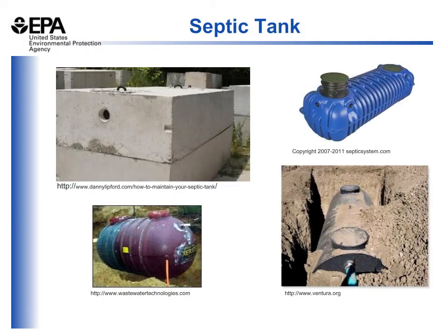Septic tanks can be built from a variety of different materials. Often they are constructed out of precast concrete, typically in two parts with the bottom connected to the top as the system is being constructed in the field. They can also be built out of fiberglass or polyethylene plastic, or in some cases steel, although metal tanks tend to corrode when they sit in the soil for some time, allowing effluent to escape the tank.